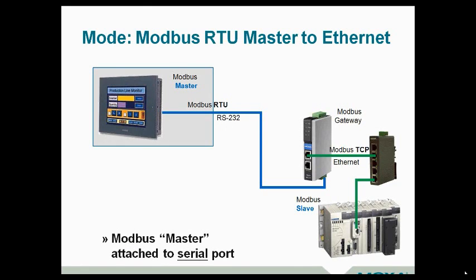Some of you folks mentioned that you'd actually done some applications with gateways, and let's take a look at some of those. Now, we used the example of having the Modbus RTUs being only on the serial side. You can actually use these in a reverse configuration, and it looks like this. So if you've got an HMI and the HMI only talks Modbus on serial, you can use this in a backwards configuration where you can have that HMI pull data from an Ethernet connected PLC. Pretty useful way, and again, all you need to do is go into the mode settings and change that within your gateway.